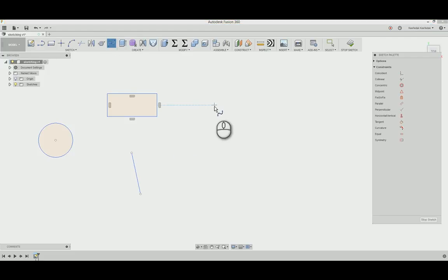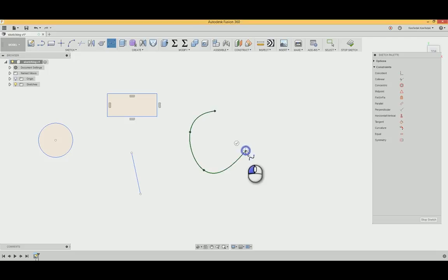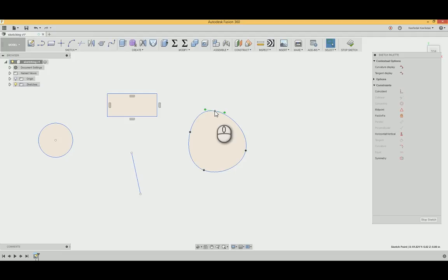And with that, you're going to just click, click, click, a bunch of them, and then join them up together. Once you've got it joined together, hit escape. I tried to remove line from my toolbar, and I made all of it go away, so now I can't see. Then watch: you go up to your toolbar anywhere, right click, reset all toolbar customization. Or you can reset the panel, whatever. Okay. Thank you. You're welcome.